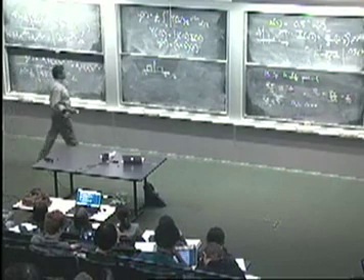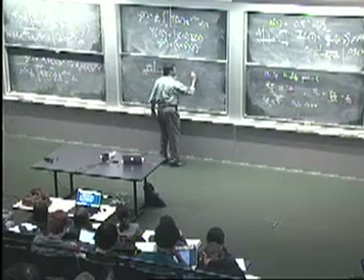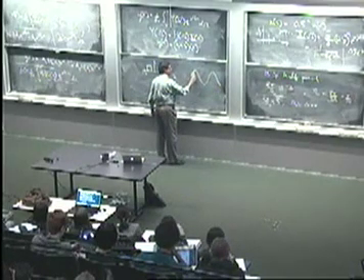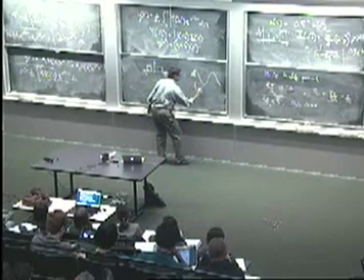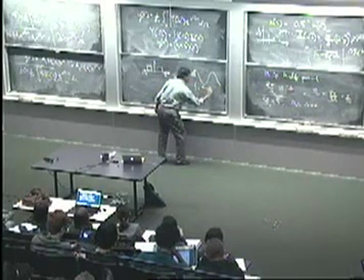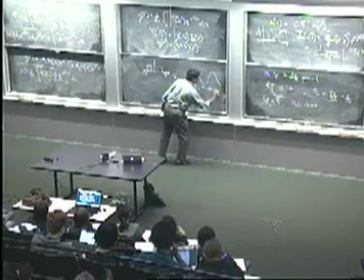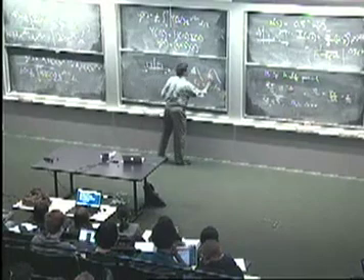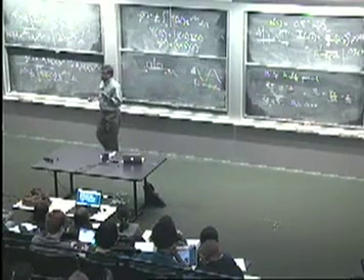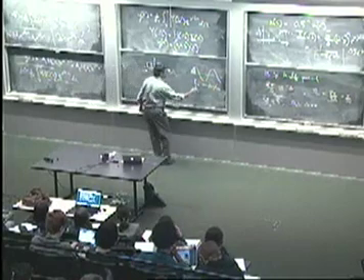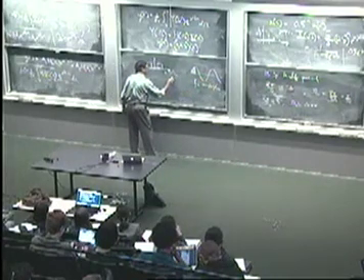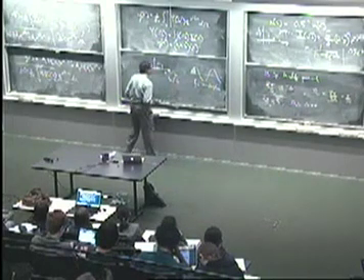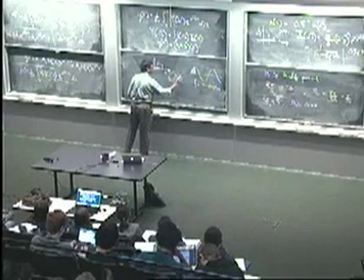So you actually need a way to go from an underlying continuous time signal that's sampled at a particular sampling rate, let's say f_s samples per second, to a corresponding omega for the underlying discrete time sequence. Okay? So the question is, how does f_s map to omega? And I had a slide last time. I haven't gone through it in detail. Maybe we'll have you work through it on a homework problem, but this is actually the mapping.